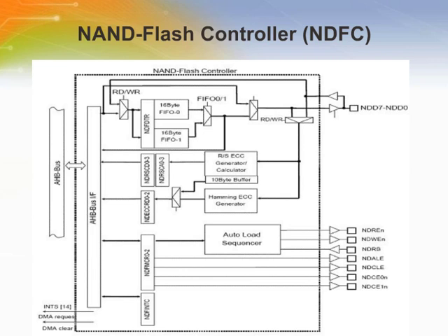The NDFC has the following features. It controls the NAND-Flash memory interface through registers. It supports 8-bit NAND-Flash memory devices. It does not support 16-bit devices. Supports page sizes of 512 bytes and 2048 bytes.